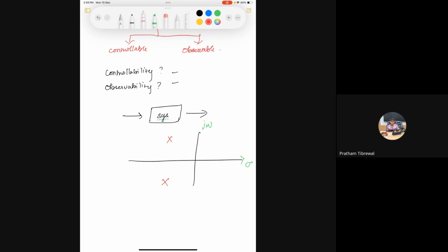And how well it is going to perform will be decided using the location of poles and the location of zeros, right? So if both systems are stable, which system is going to perform better depends on the location of the poles. But both systems are in the stable region. This is where we draw a line between stability and performance.